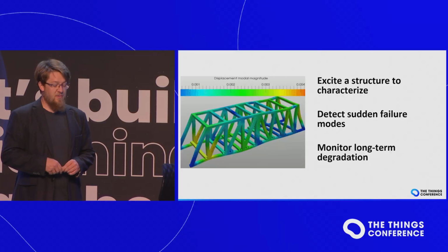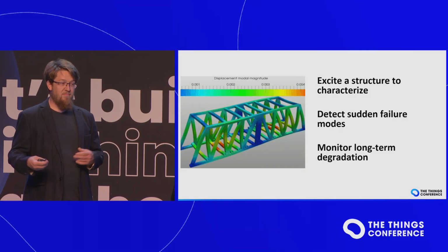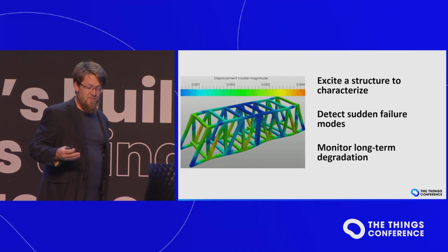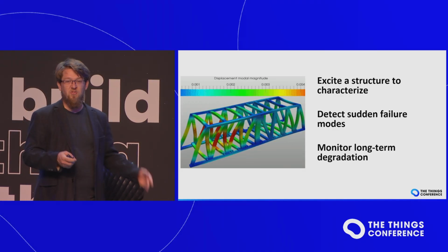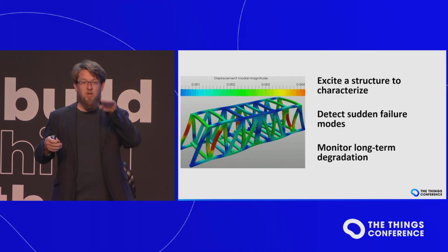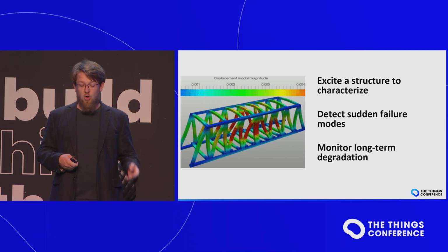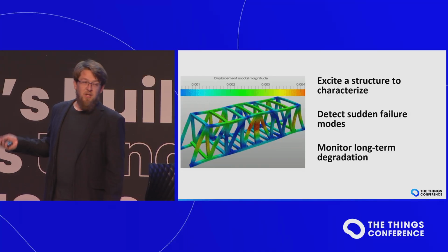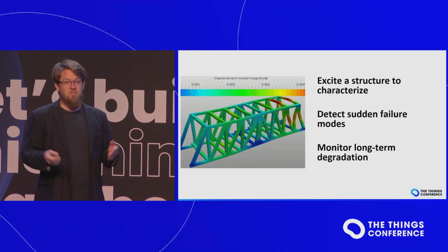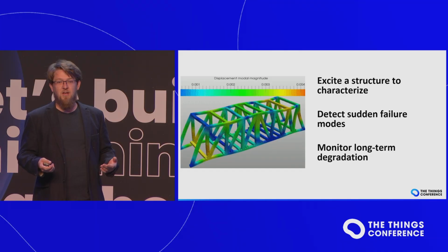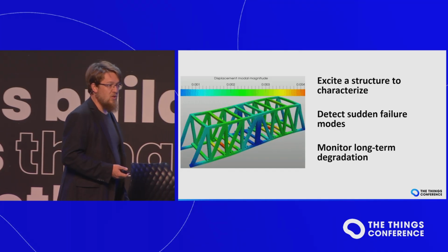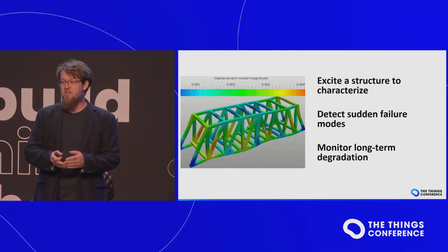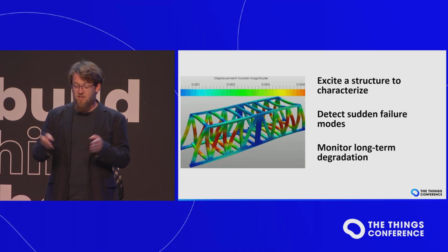So specifically diving into all of this, when you look at the bridge, for example, you will see it wobble about this way. So if at every point of the bridge you put an accelerometer, you will see that point moving up and down and left and right. Or you put a strain gauge or any other kinds of sensor. Now the speed of that wave and the vibration is often pretty fast. You will be looking at things up to a few kilohertz. So the timing between those samples needs to be very precisely aligned between all the points.